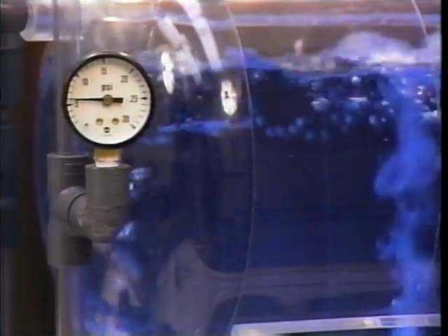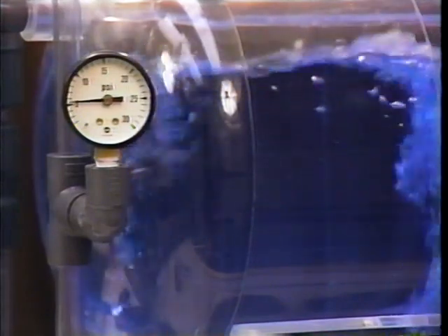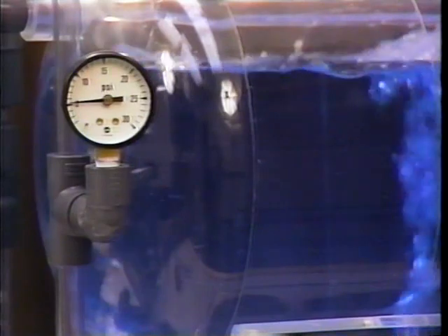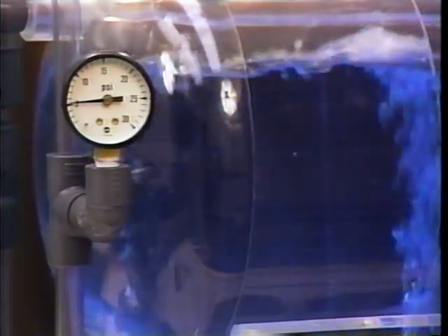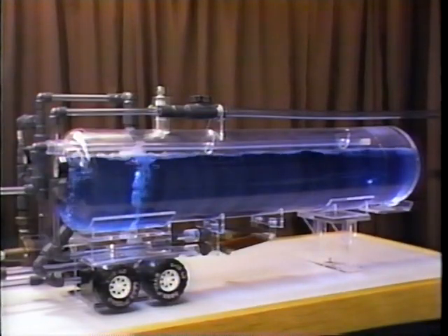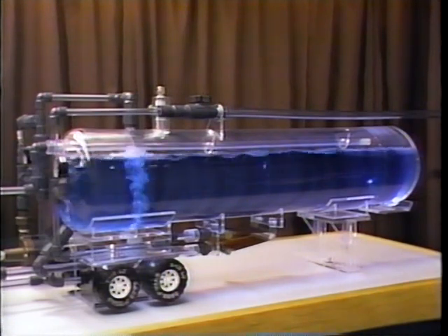As the pressure of the saturated product begins to drop, the liquid begins to boil and evaporate. It is trying to cool down to a lower temperature that corresponds to the lower vapor pressure condition being created by the venting. Since this is a horizontal tank, the boiling takes place over a rather large surface area and is not too dramatic.